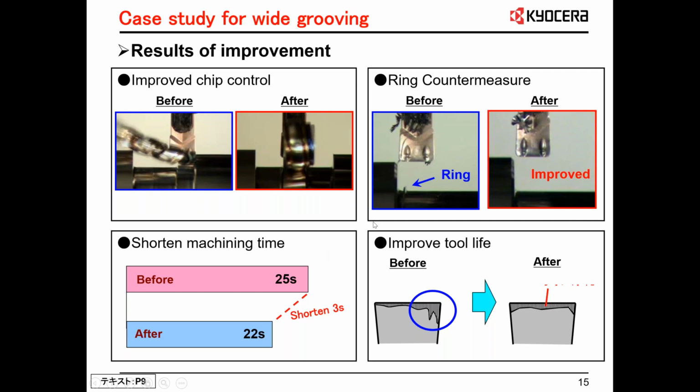So you always want to do your plunging offset: 1, 2, and then in the middle 3. That way the tool is completely engaged every time it plunges, and so there's even wear across the nose, which is what you want to see.